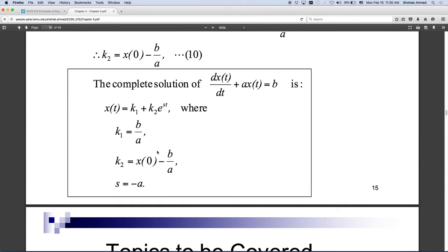And if in the transient response, if this x of t I solve for inductor current or capacitor voltage, I put t equal infinity. What am I saying? I'm saying, what is the steady state solution? Right? I'm putting t equals infinity. So do you have to go and solve this system of equations? You don't. You just have to make any capacitor open circuit, make any inductor short circuit, and divide V by R. Okay?